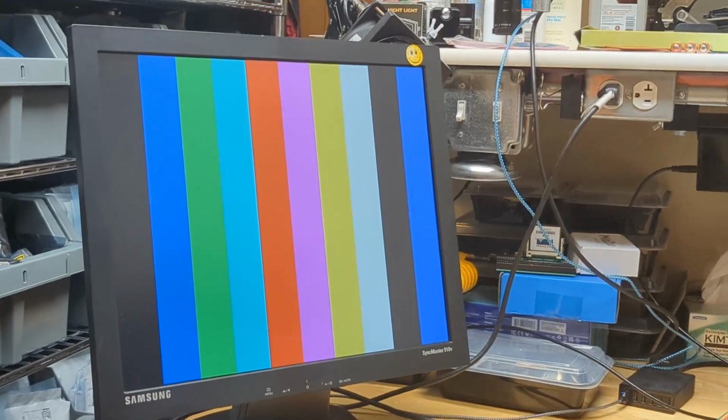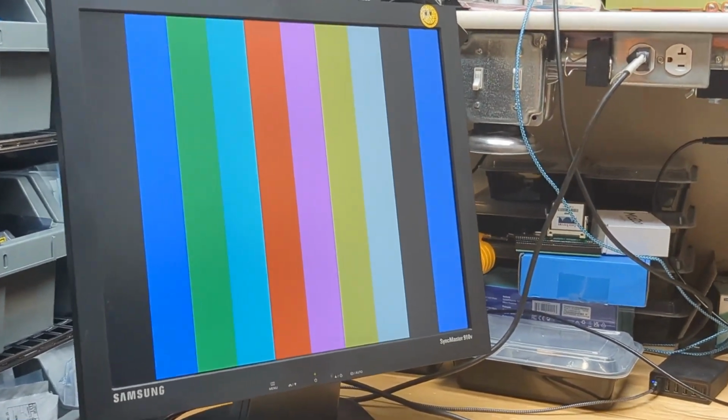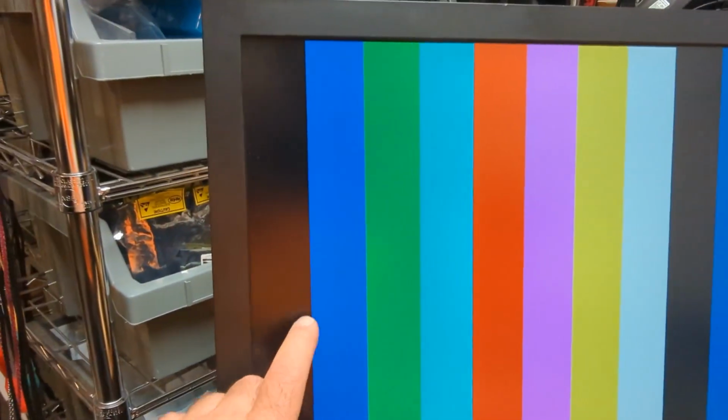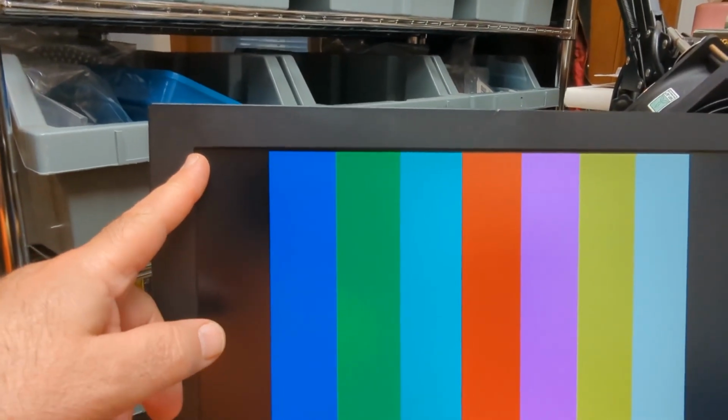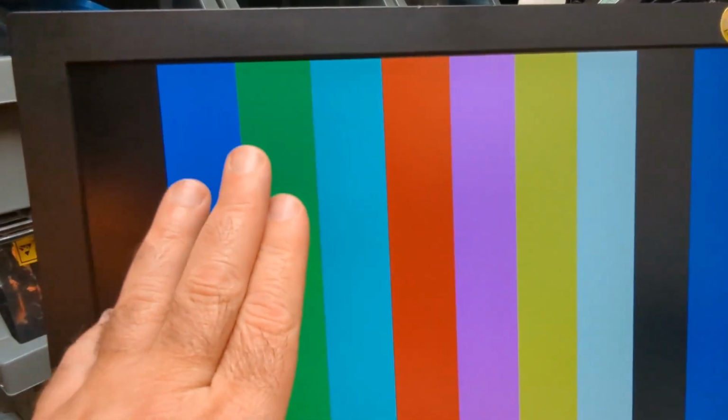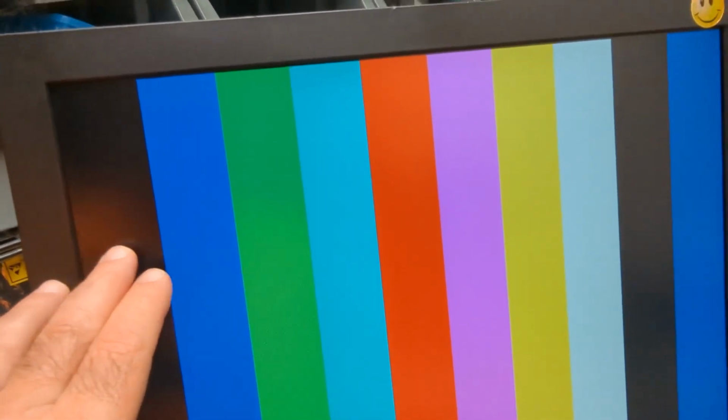And there you go. That's what we get to see here, which is pretty cool. So what do we get here? We see black on the left, and that makes a lot of sense, really. Why? Because remember that pixel 0 and row 0, I should say column 0 and row 0, are up here, the far left edge of the displayable area. We know all 3 most significant bits in the counter are 0 over here, so it makes sense that they'd be black. As we move over here, of those 3 most significant bits, we have a 0, 0, and a 1. And they're plugged in, I'll bet, to red, green, and blue.